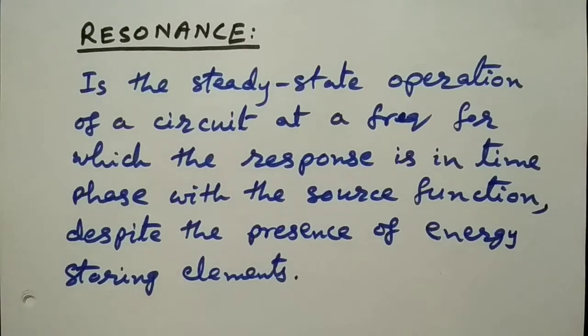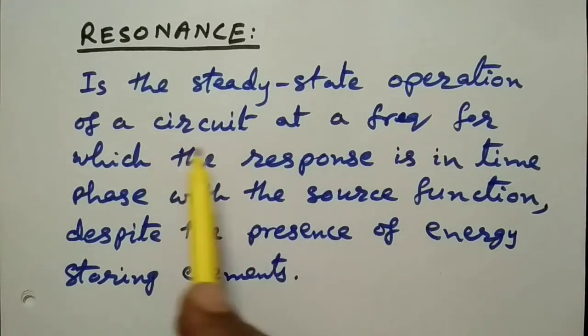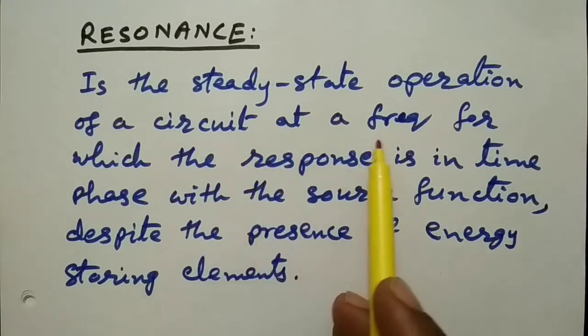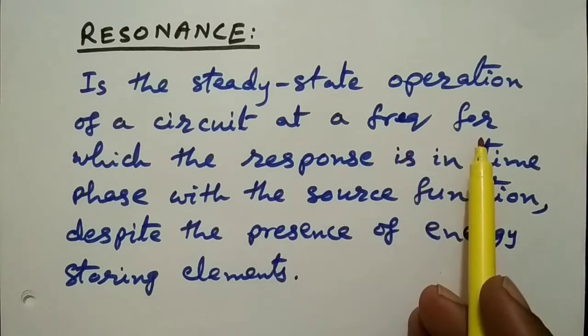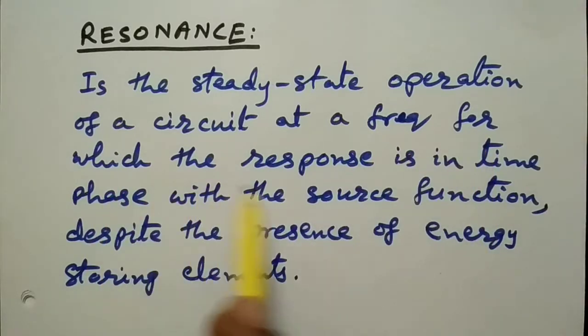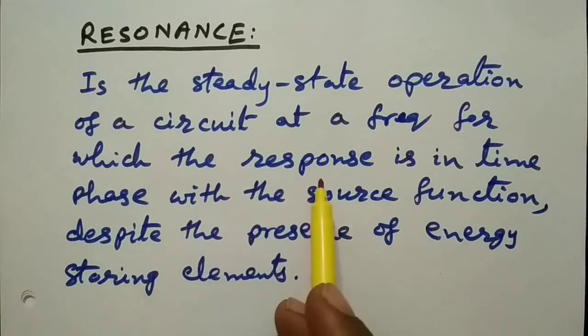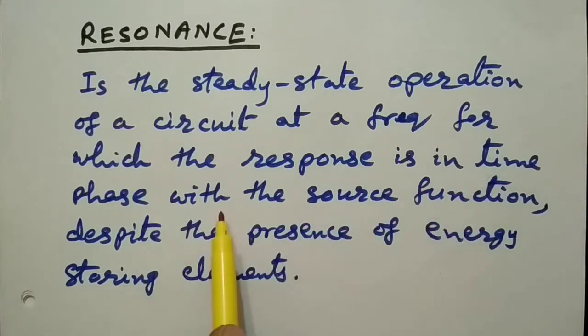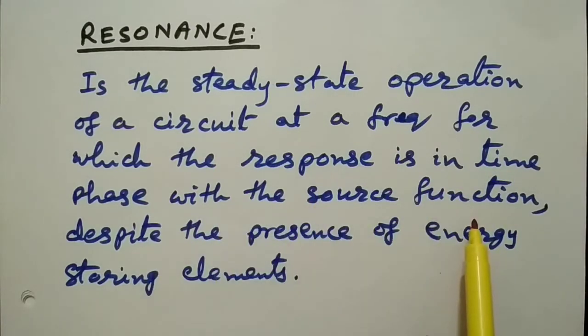So resonance is defined as the steady state operation of a circuit at a particular frequency for which the circuit response is in time phase with the source function despite the presence of energy storing elements.